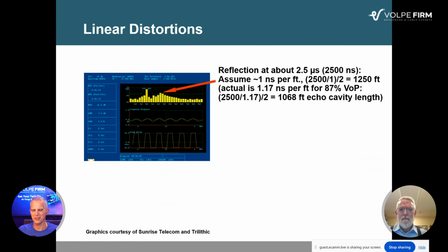So we've been using digital taps in the downstream to find echo cavities the same way that we're using digital taps in the upstream in pre-equalization analysis for PNM. Yes. So this isn't anything new. We've been doing this for a long time. Long time. This goes back, I think I took these screenshots back in the 90s. Yeah, so long before we were doing PNM.